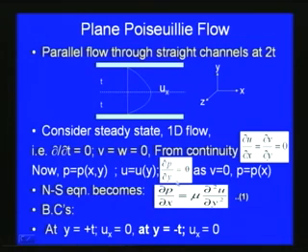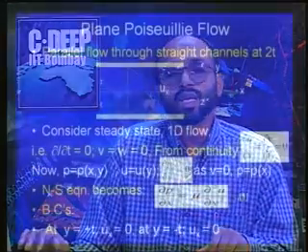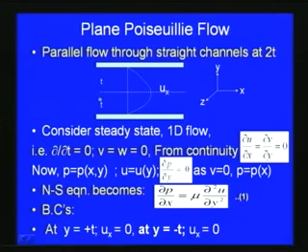So, now we got the governing partial differential equation. Our aim here is to get the velocity variation or the pressure variation, as we have discussed earlier. Now the boundary conditions: there are no initial conditions, since we consider the flow steady state. The boundary conditions we are using are the no slip condition. With respect to this figure, on the plate, at y is equal to plus t and y is equal to minus t, the velocity is 0. So, the velocity variation will be parabolic like this.